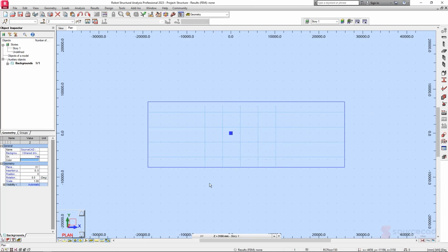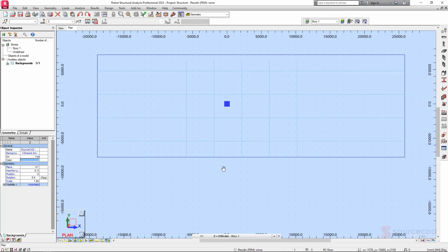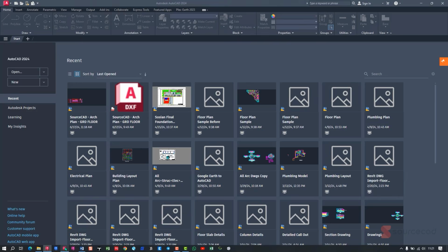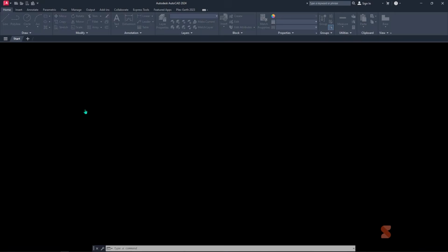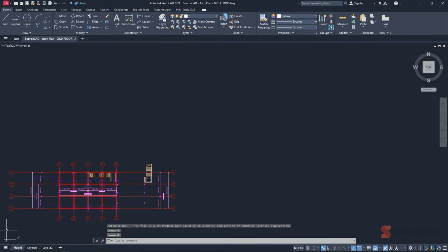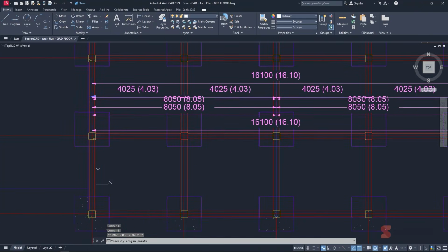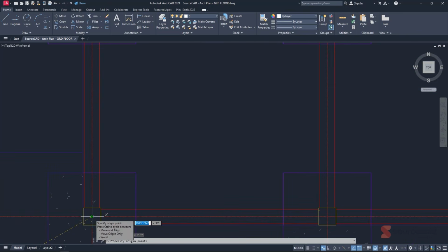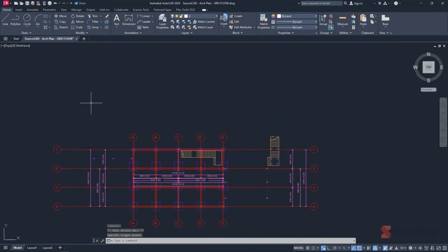So click on OK. And let's say in the event that in our AutoCAD, we want to do some changes. This is a specific drawing that we have. So I can open it like so. And I can, let's say, move origin. I want to move origin only. Then I can move it, let's say, to this specific point. And this is the way you specify your point. So I have specified my origin point.